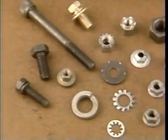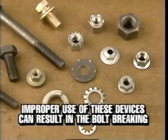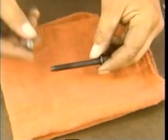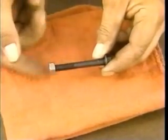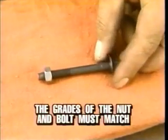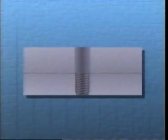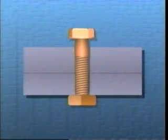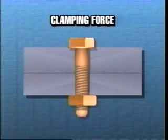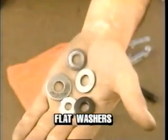Bolts have many uses, and certain devices help them apply the right clamping force. Improper use of these devices can result in the bolt breaking. When the application requires the bolt to penetrate the clamping surfaces, a hex nut works with the bolt. Remember, the grades of the nut and bolt must match. Again, bolt stretch and surface compression during tightening results in clamping force. The threads of the nut stretch with the bolt threads.